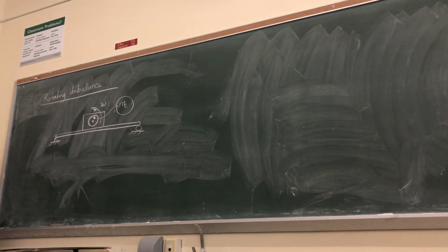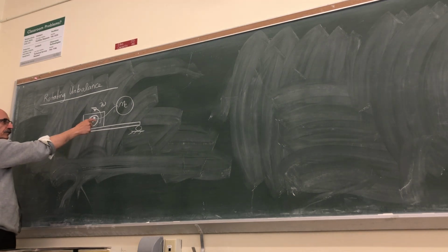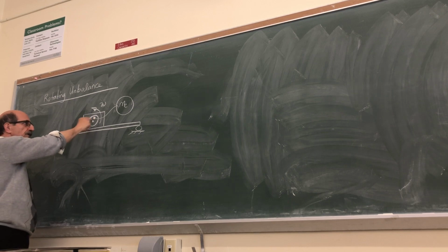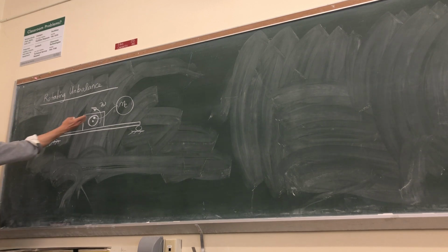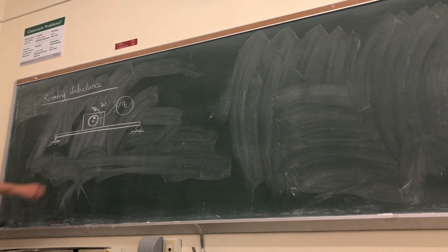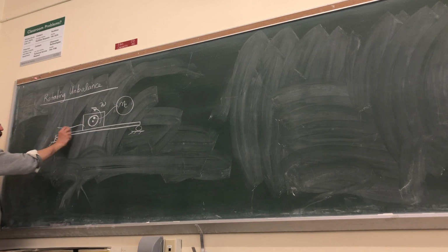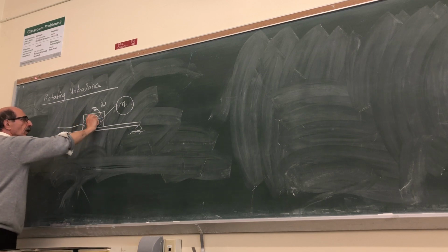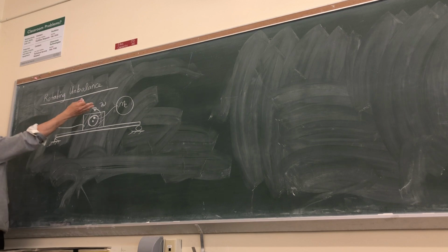That's what E stands for, basically a mass that has caused the center of rotation not to coincide with the center of mass. Because you have a little guy that is really disturbing the whole distribution of the mass, okay? So the total mass of this piece of the machine includes that, right? The remaining mass is M minus m_e.